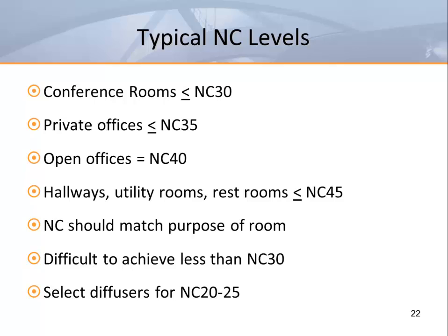The next loudest space would be a private office specified not to exceed NC35. This gives a supervisor or manager a good environment for meetings with employees, talking on the phone, reading and writing. The ability to close a door for additional sound reduction and privacy means that nothing special in the way of equipment is typically required beyond that serving the louder adjoining spaces.